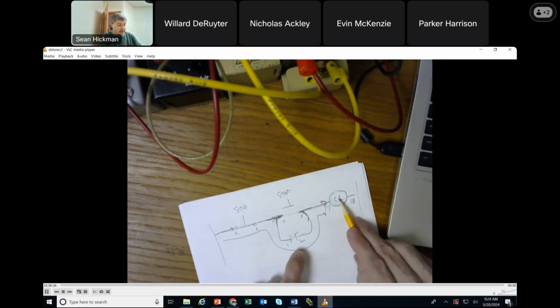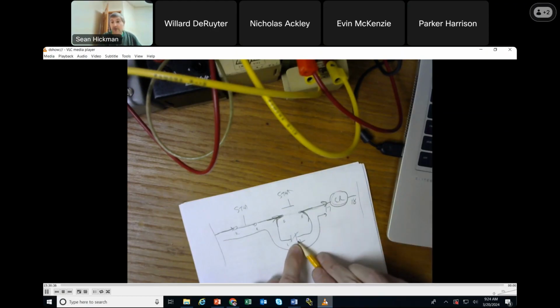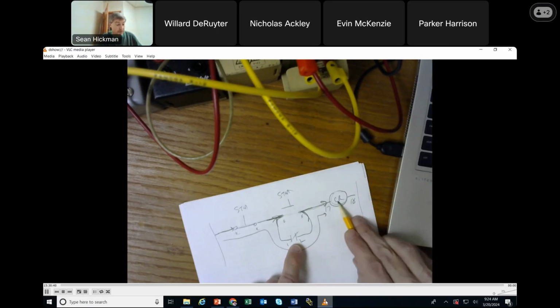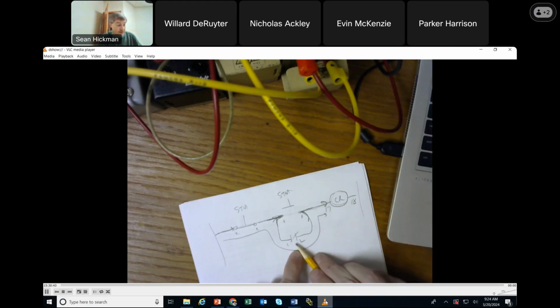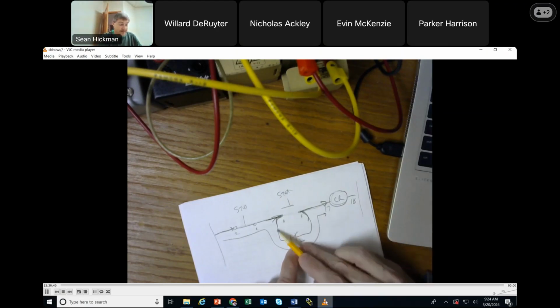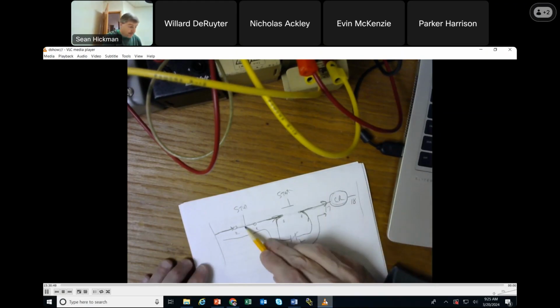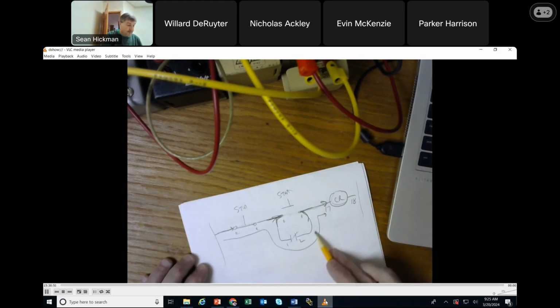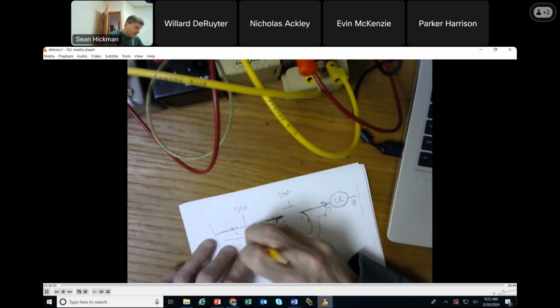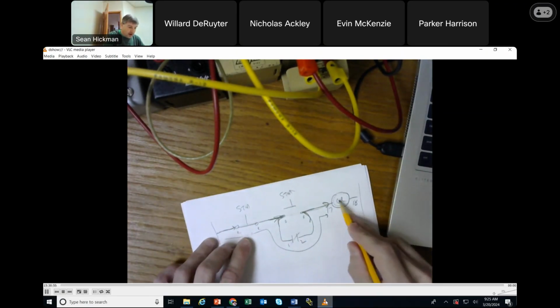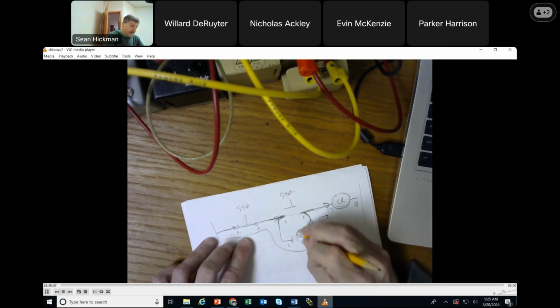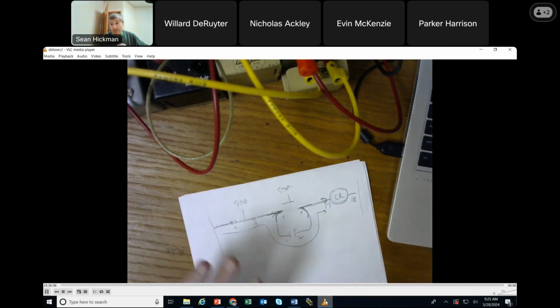So this control relay closes, and it kind of turned itself on, because the control relay closes 1 and 2. So when I let go of this, I've got this alternate path right here. And then when I hit stop, this breaks, which means that this goes off, which means that my contacts here open.